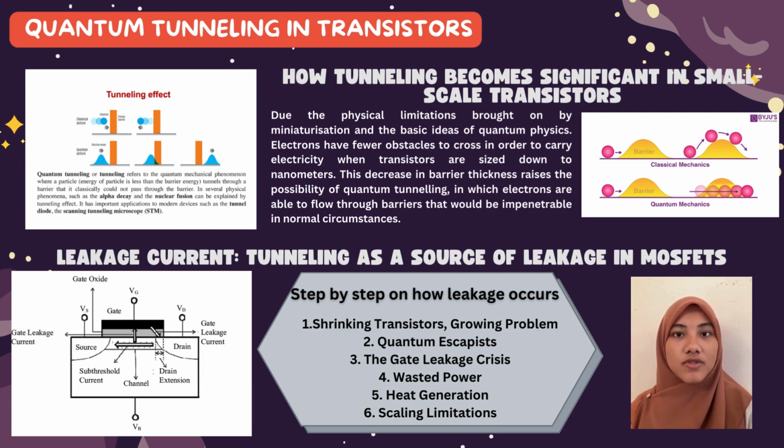Next, tunneling becomes significant in small-scale transistors due to the physical limitations brought on by miniaturization and the basic ideas of quantum physics. Electrons have few obstacles to cross in order to carry electricity when transistors are sized down to nanometers. This decrease in barrier thickness raises the possibility of quantum tunneling, in which electrons are able to flow through barriers that would be impenetrable in normal circumstances.